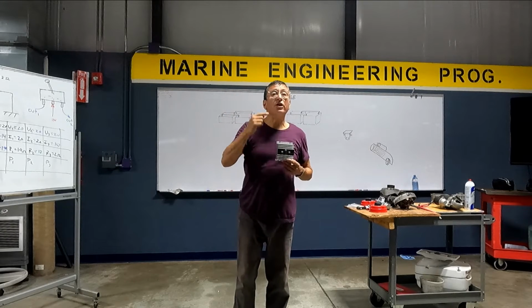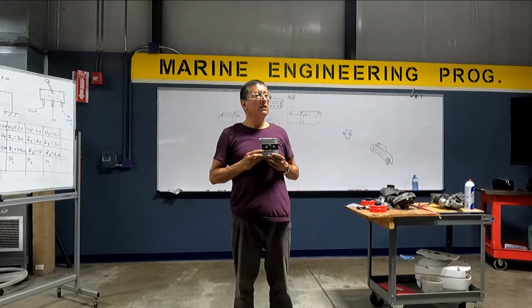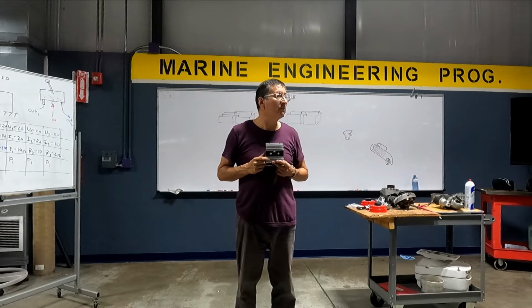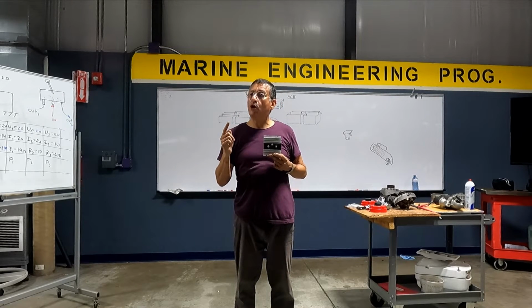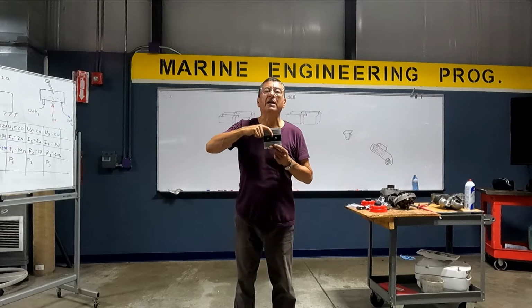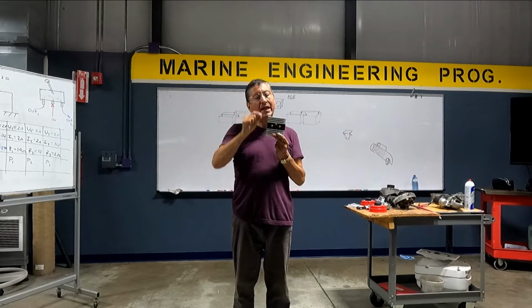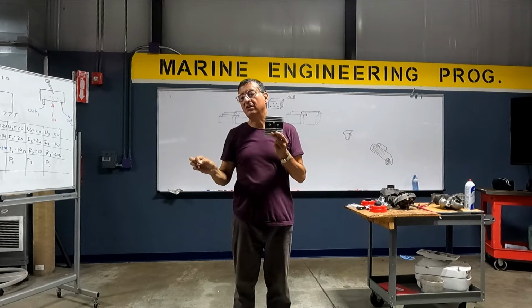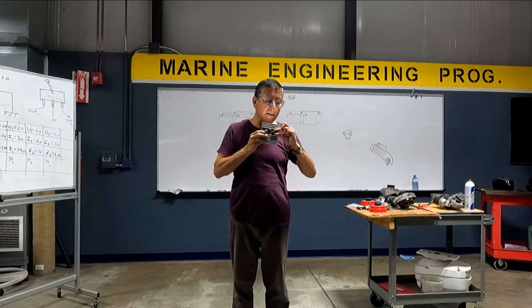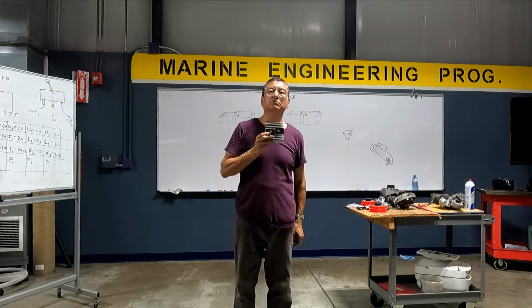When the engine is running, the alternator produces DC power. The DC power coming out from the alternator enters here, in the middle. This is the input. And in each output, I connect the positive of battery bank number 1 and the positive of battery bank number 2.